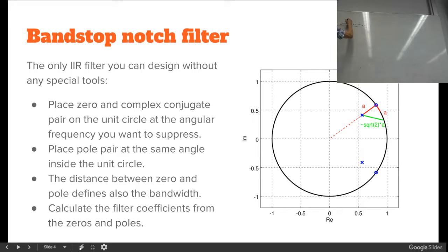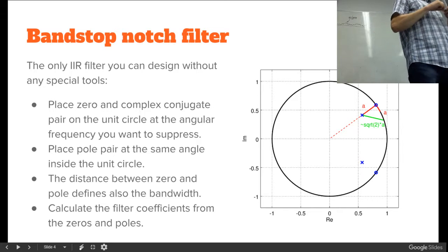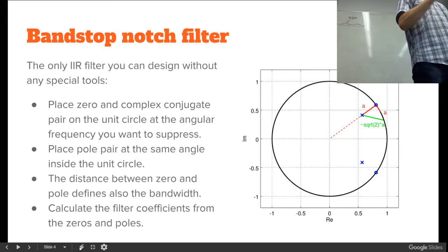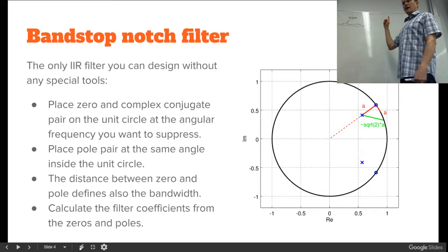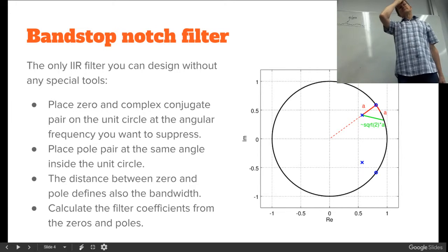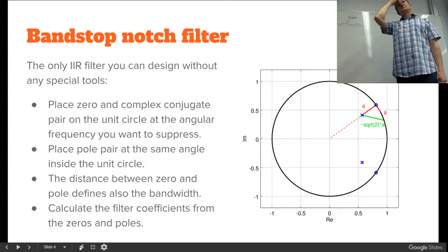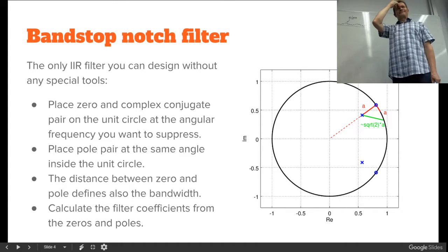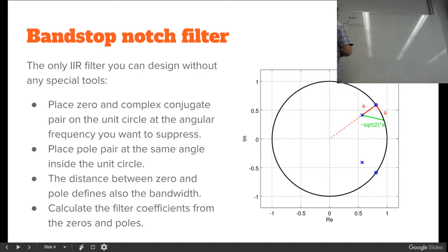And actually you might have the 50 Hertz or 100 Hertz. 100 Hertz is usually a more usual disturbance than 50 Hertz because of the regulation. With AC to DC conversion you will get 100 Hertz ripple. And well, those are also good sources of all kinds of noise.